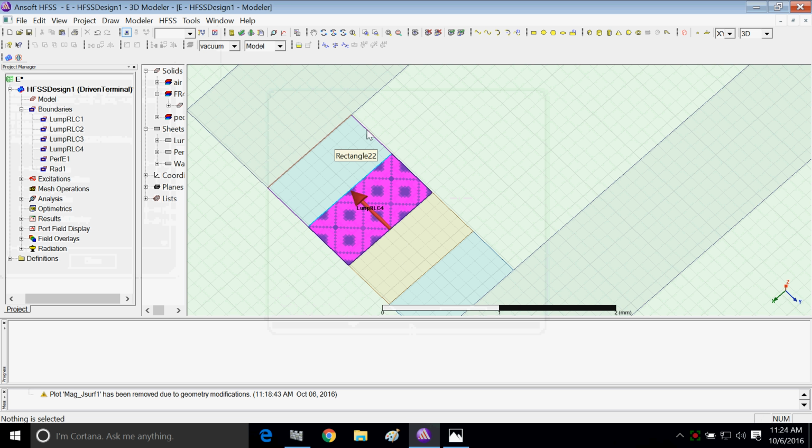Now about the size of these sheets, you can take it depending on the practical size of your PIN diode. Generally if you are going to take chip diodes, the dimensions are around 0.7 or 1 millimeter. Similarly for capacitors also it is in the range of few millimeters, 0.7, 1 or 1.2 millimeters. So you have to take an idea of which type of components you are going to place over here and what should be the spacing between these two. You will have to take care, because the soldering itself is a complicated task, because the devices are very tiny, and also after that you have to place the wiring over here. That care you are supposed to take.